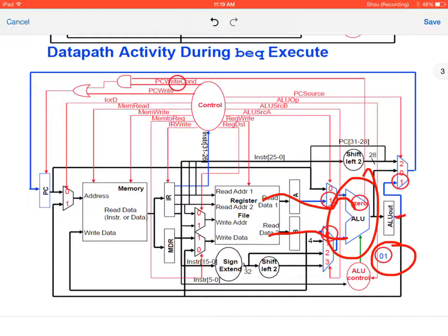In the previous stage, now this is where the clocking becomes important, from ALU out, we have calculated the branch address, right? So this is where reuse of the ALU becomes important. We have clocked, we have moved the address that we're going to branch to here. We're then going to move to this to 1. So it's going to be 0, 1 from PC source, right?